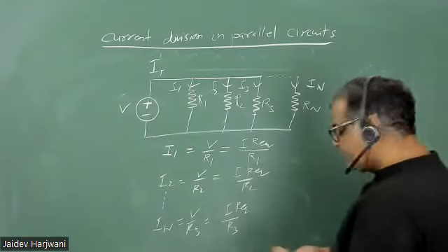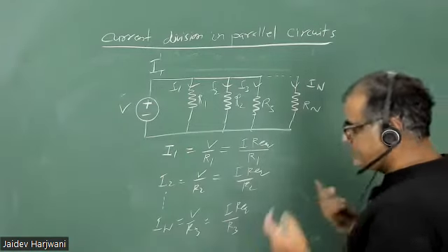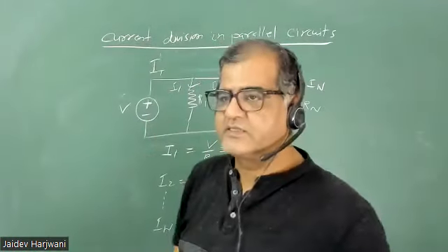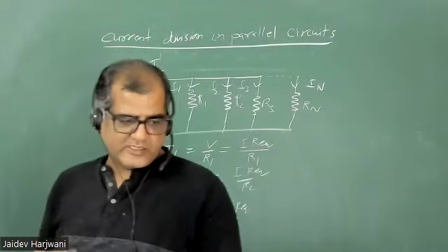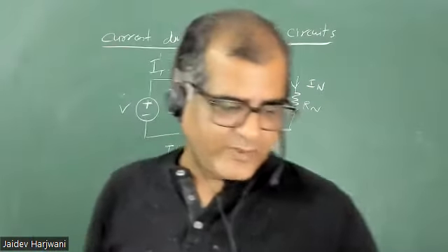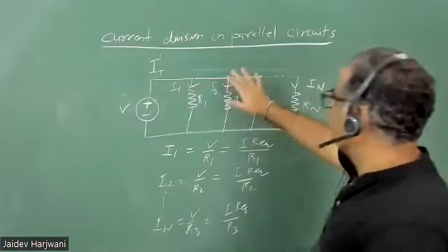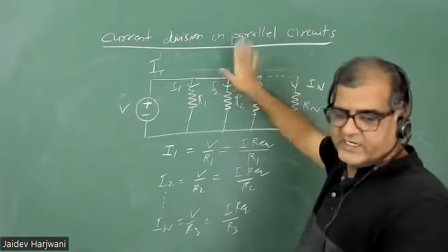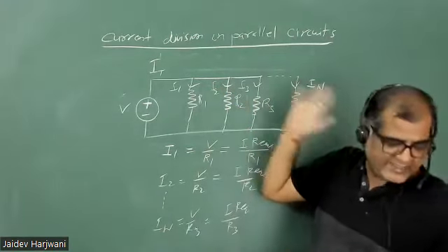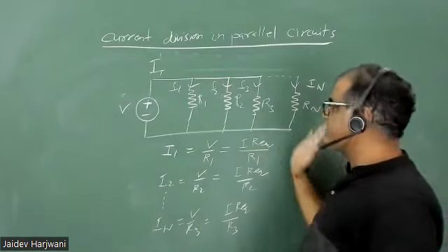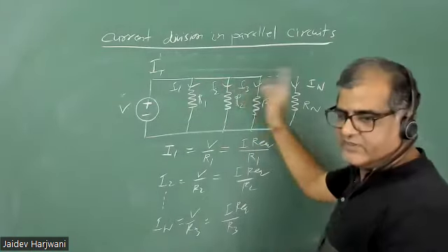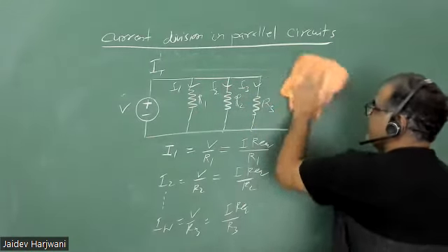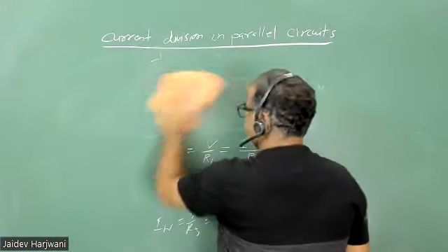Now generally in this course, several times we will see this current division come up whenever I solve circuits, or when we use diode, transistor, op-amp. So this is very useful, current division. You have to learn how to apply current division. Here is the n resistance case, but I am solving this for a simple 2 resistance case, because the 2 resistance case will come again and again. So let me show how to apply current division if there are only 2 resistances in the circuit.